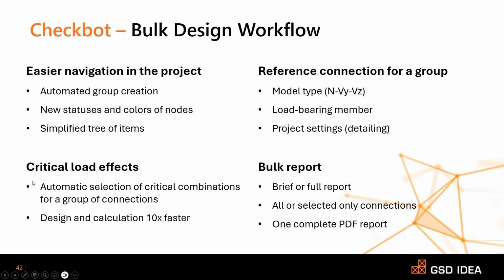And if you are working with a global model and import the information into your Checkbot, then you might have a huge number of load combinations, maybe around 200 to 500 or something. Checking your connections for that many load combinations will consume a lot of time.